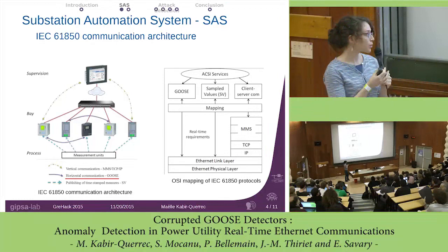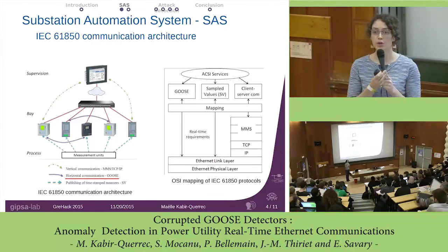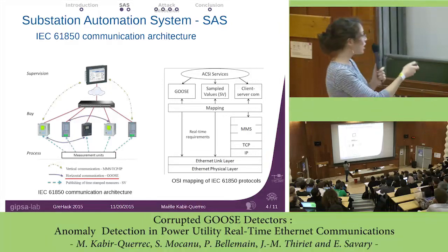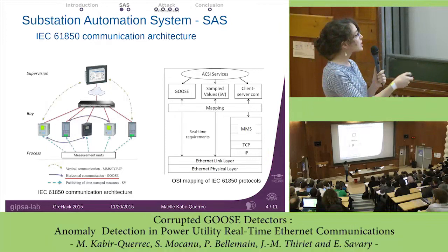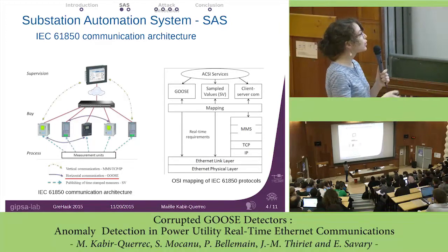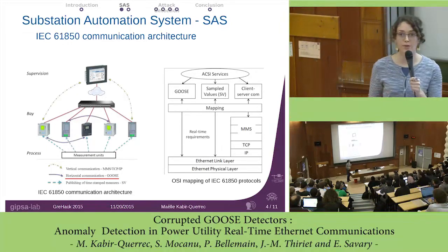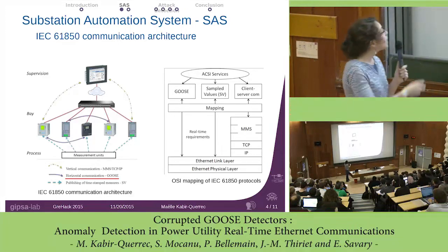So there are 3 protocols involved according to the units exchanging information. Measurement units will send their measurements to the IED through the sampled values protocol.